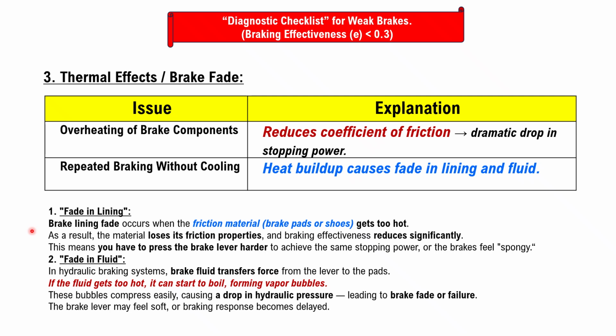Number two, fade in fluid. In hydraulic braking system, braking fluid transfers force from the lever to pads. If the fluids get too hot, it can start to boil, forming vapor bubbles. These bubbles compress easily, causing a drop in hydraulic pressure, leading to brake fade or failure. The brake lever may feel soft, or braking response becomes delayed.